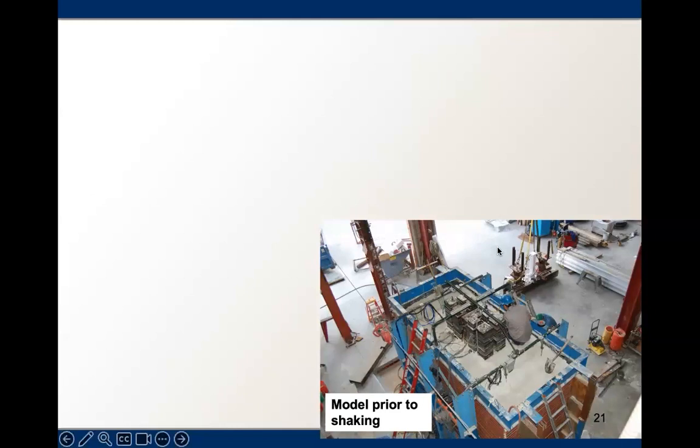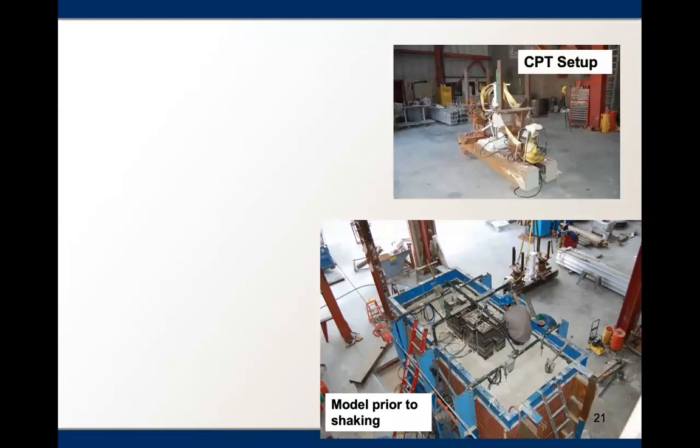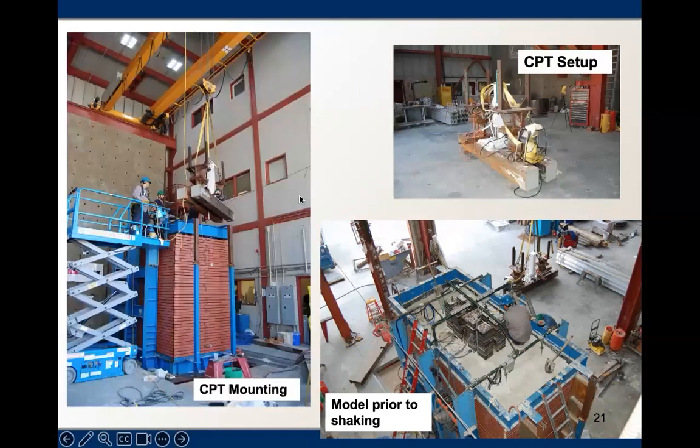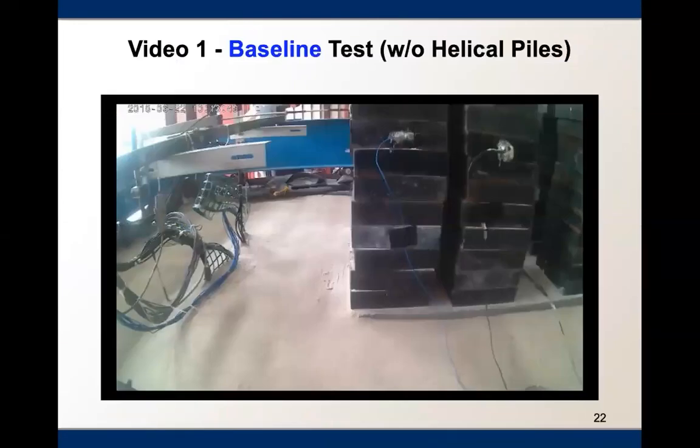We characterized our model using cone penetration testing. You see the CPT setup before and during measurements. So we repeated the CPT before every shaking sequence, and also at the very end of the testing.